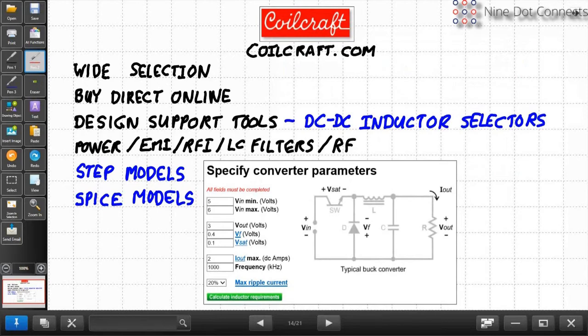Are the shields connected to ground? Not necessarily. Magnetic shielding does not need to be electrically connected to ground at all. It's only if you're worried about electrical fields coming off of a coil, which can happen. Let's say you have large voltages on this coil. The whole coil, the wire itself, may be going up and down in voltage, and that may radiate, and may require some kind of electric shielding.